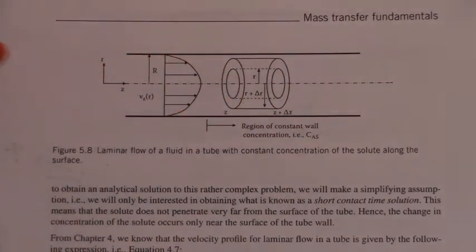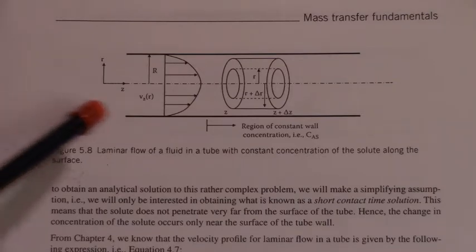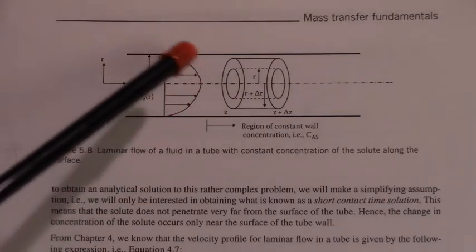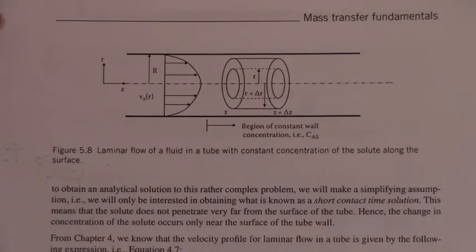In this previous region over here, remember the fluid comes in and the velocity profile is going to be flat as it makes contact with the tubes, and then as it starts to flow, the velocity profile develops. So it takes a certain distance before we get this fully developed velocity profile.